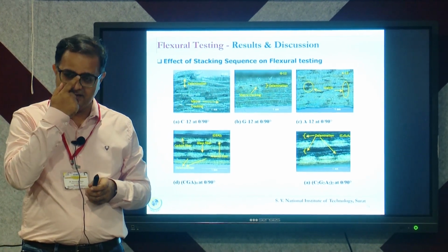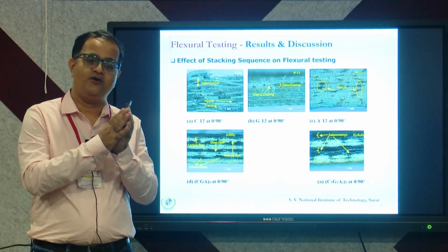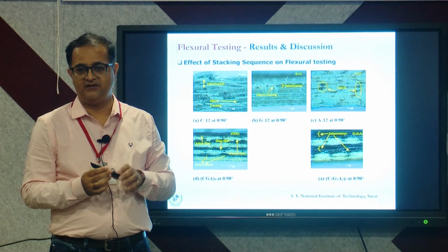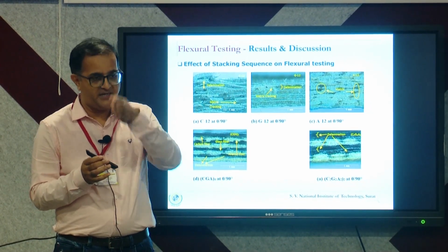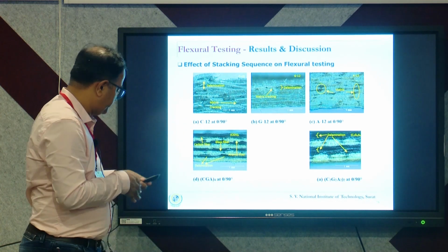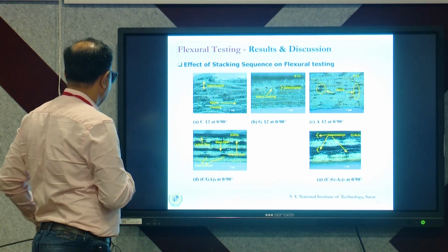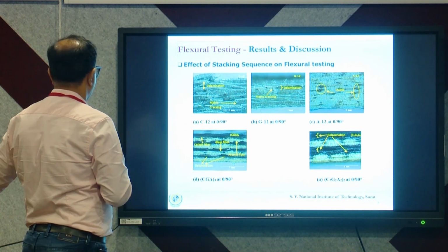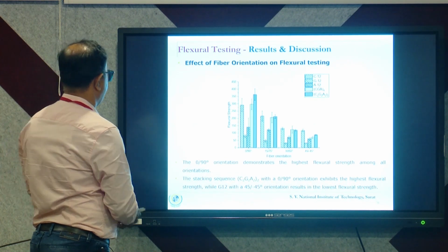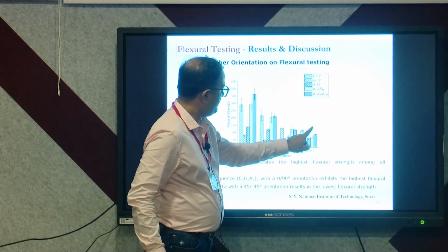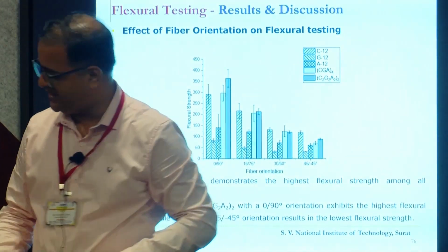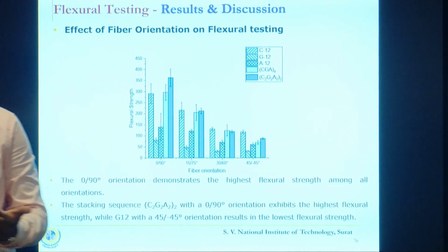When there are other inclinations, they do not have an option, they always get delaminated, and you may also observe that they may start breaking in the case of 45 degree. I think I have that graph, that observation also, depending on fiber orientation. See, 45 gives you the minimum results, because they are placed in one particular way, this way.